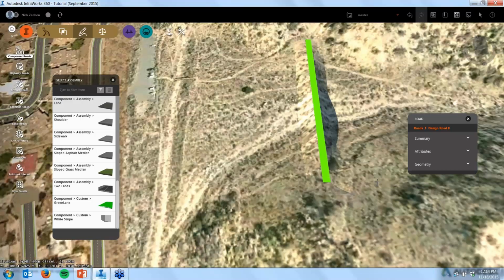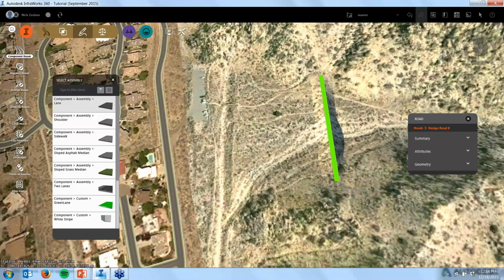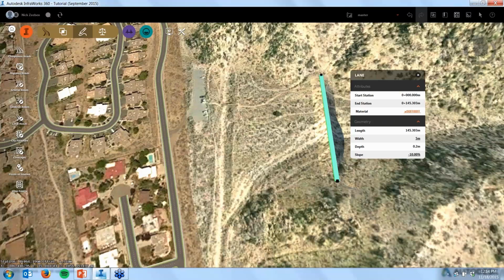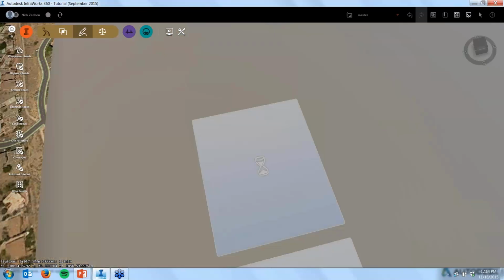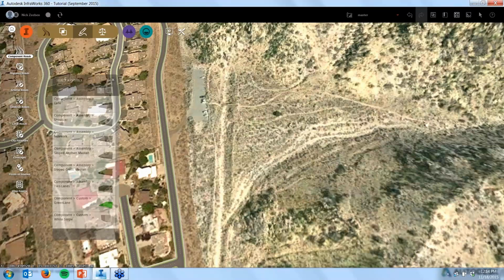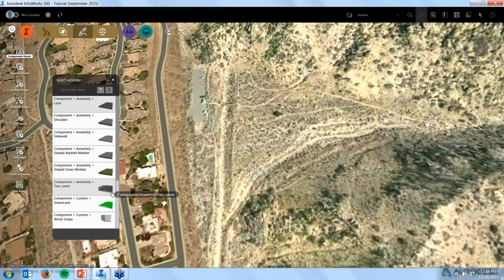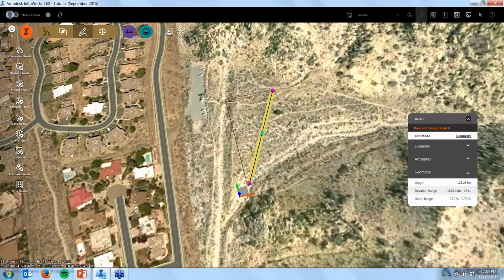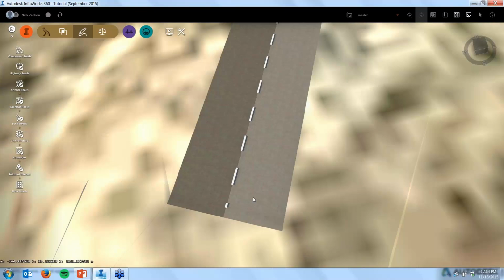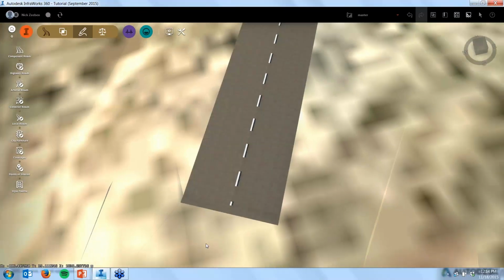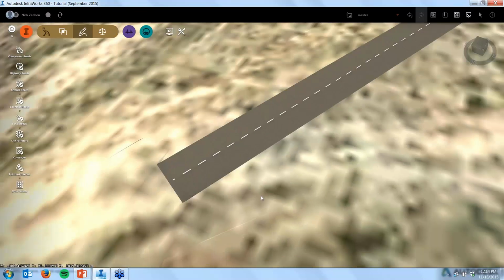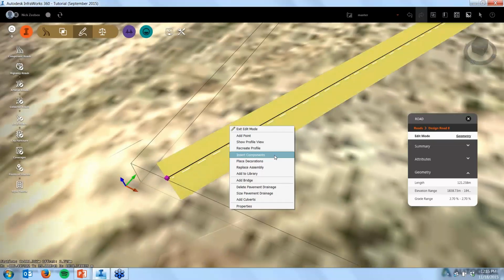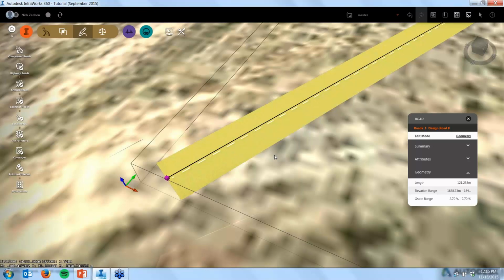So what I'm going to do, my creation here, I'm going to create a new little access road, and we'll look at maybe a proposed road subdivision type option in this area. I'm going to create a new configuration of roadway that is going to represent what I want for my subdivision. I'm just going to start off with a 2-lane undivided, and I want to add some more detail. We'll start to look at the creation workflow a little bit here, but we'll look at it later in a little more detail. So I'm just going to add another component.